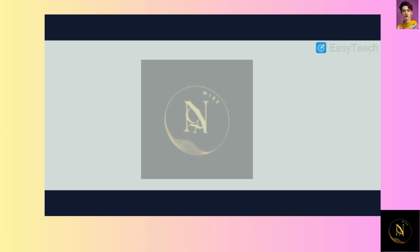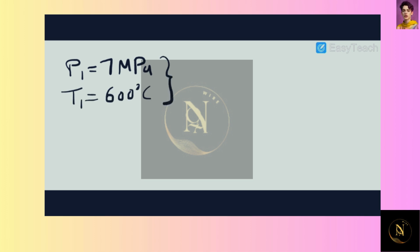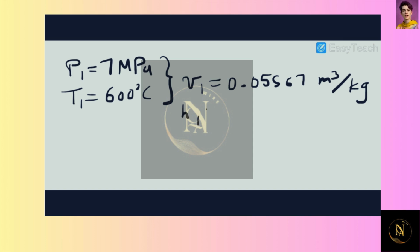Next, using the states that are given to us, we can determine some parameters. So we know the input pressure is 7 MPa and input temperature is 600 degrees Celsius. Using this information, we can use the steam tables to discern that our specific volume at our input is 0.05567 cubic meters per kilogram, and our incoming enthalpy is equal to 3,650.6